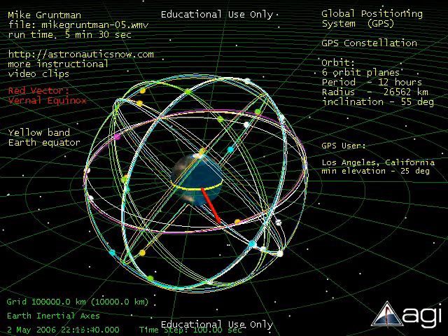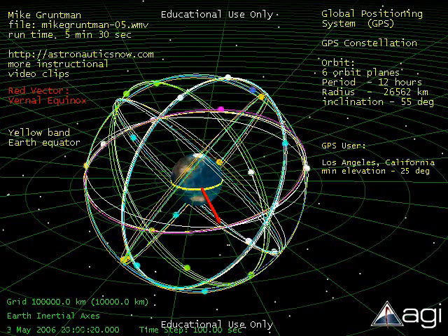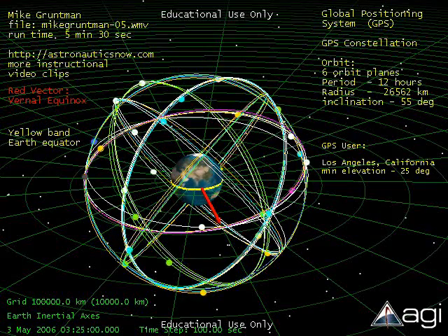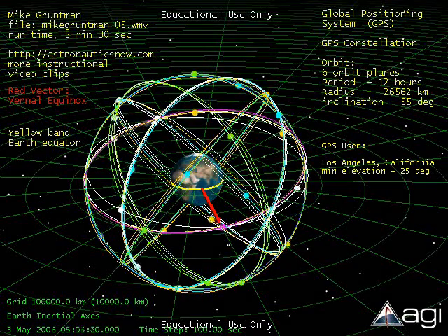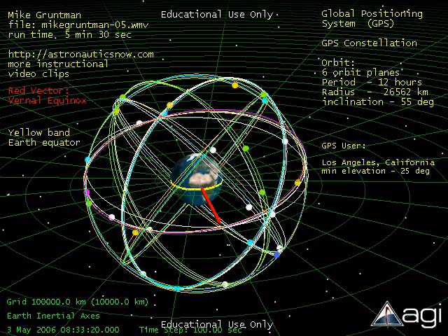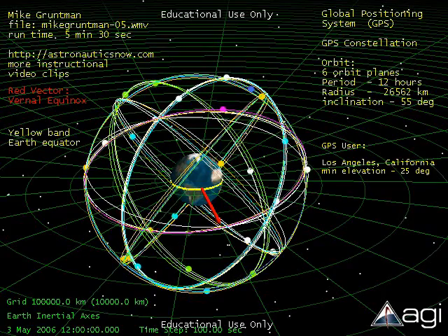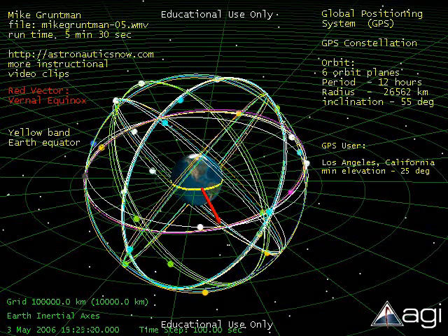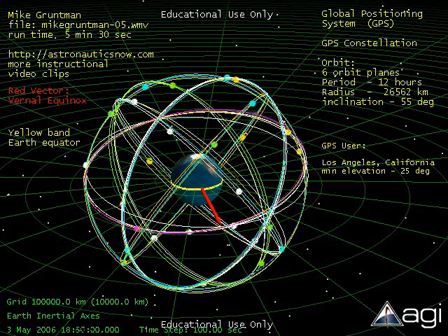The Global Positioning System provides three-dimensional position and time information worldwide, 24 hours per day, for users equipped with GPS receivers. GPS satellites transmit navigational signals. The concept is based on measuring time intervals for signals to reach the observer. The user must receive simultaneous signals from at least 4 GPS satellites.